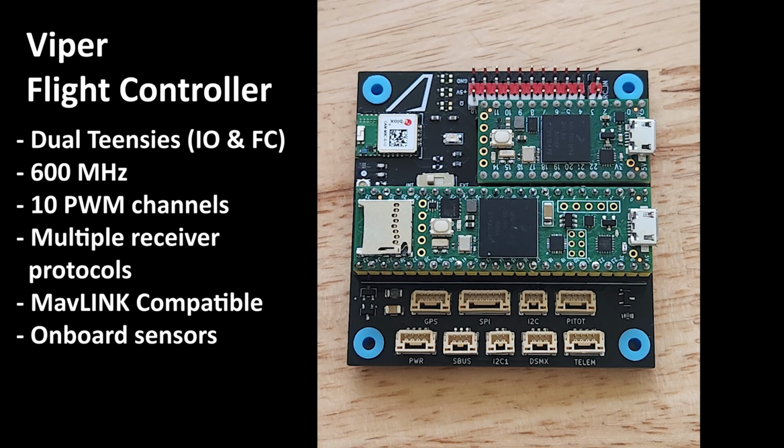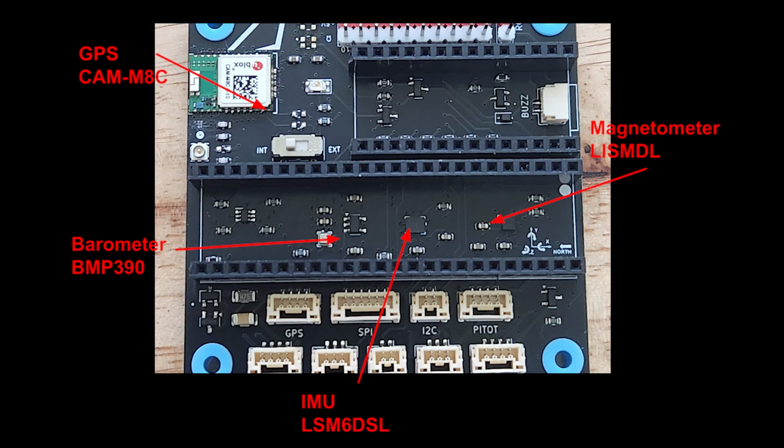Now for hardware. This is my own custom flight controller I have developed for my thesis research. This flight controller uses two Teensies, one for input-output communication and the other for sensors, control law, and data logging. The board is MAVLink compatible and has onboard sensors. These onboard sensors include a GPS, barometer, IMU, and magnetometer.